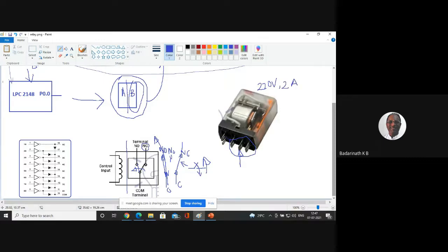For example, you are operating very high power bulbs, which you require to set up a small event in front of the house. Generally, when you purchase such bulbs, they work at 220 volts, but at very high amperes. In such cases, you require a 5 amp relay. So depending upon the bulb you purchase and the situation you are going to face, you have to choose the proper relay capability. Just imagine that the B side is working at very high voltage, 220 volts and 1 or 2 amps. No way should the B part touch the A part. If any connection happens, even a small stray connection, finish, your whole microcontroller board will get spoiled within a minute. So the A and B are physically isolated.